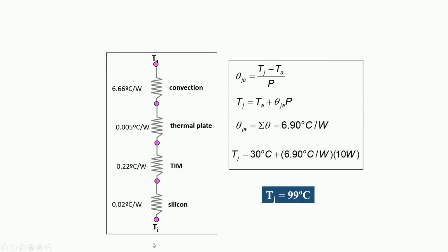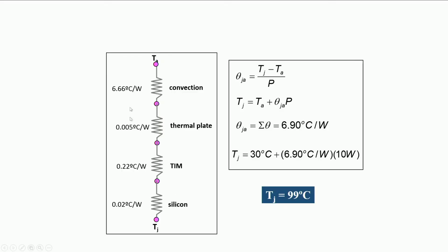Now, if you look at it, and this is again as a thermal designer, we need to have this judgment. I came up with this resistance stack, as we call it, resistance network, looked at the individual components and got some values. This should tell us what the bottleneck is. I want to increase the amount of power, given that my Tj is restricted to 100 degrees and I am already at 99, and I, as a thermal engineer, am pushing you back.